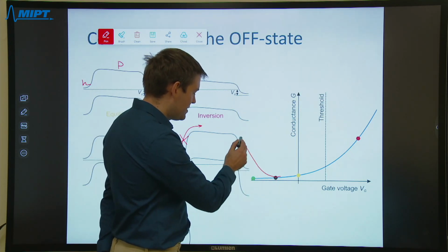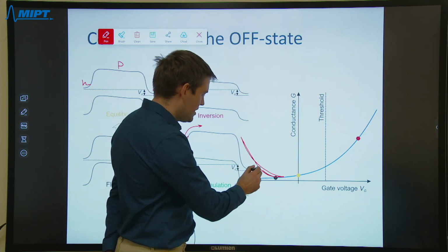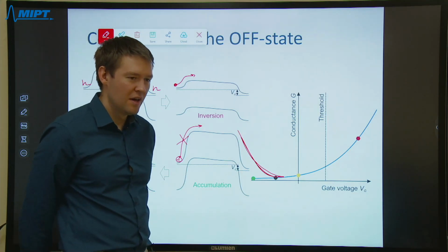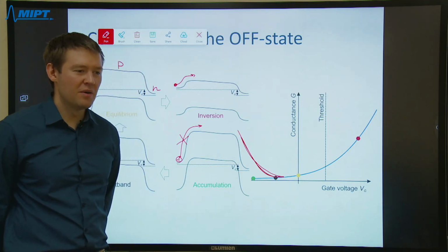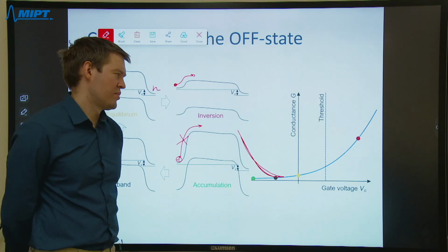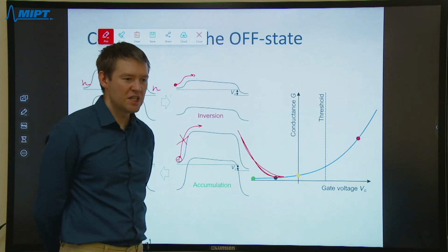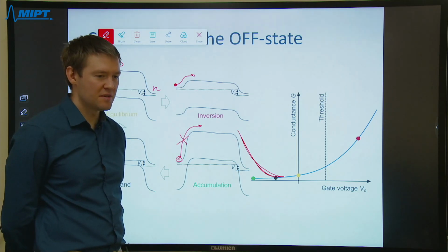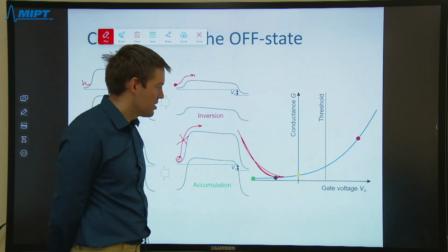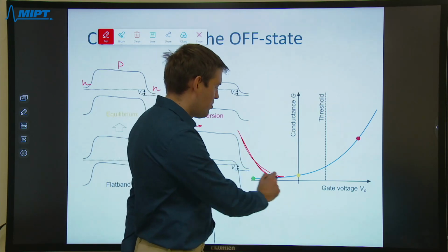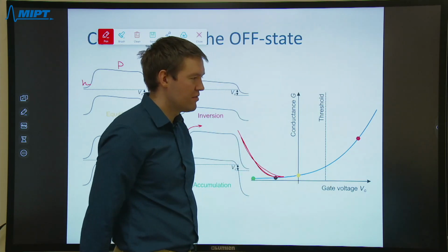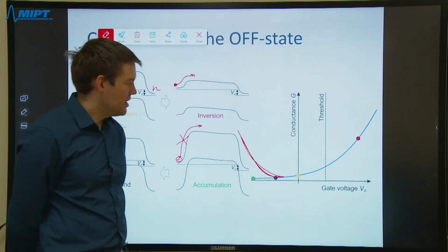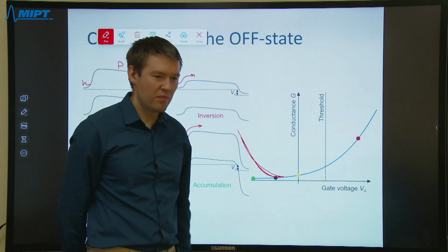In graphene-based devices, you had an increase in the conductance at negative gate voltages also. Is anybody familiar with that? And probably if not, can somebody suggest why in several kinds of transistors the conductance goes up both at positive and negative gate voltages, while in typical silicon transistors it goes up only at one polarity?